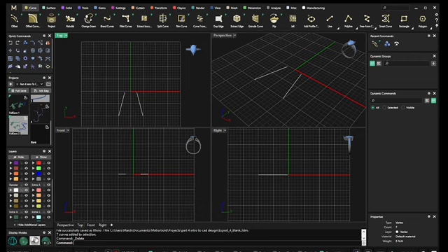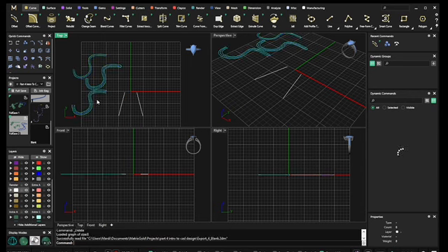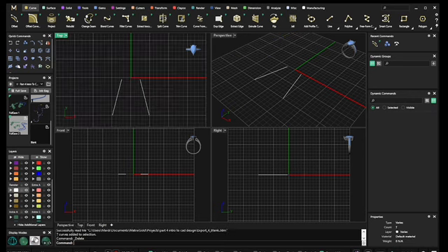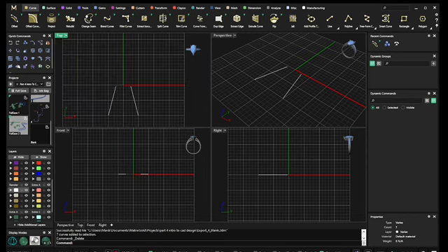So all I did to put it in the job bag as a little reminder was I pressed down on this arrow, and now if I want to bring it back into the viewport, I click in the middle of that job bag and they reappear. So it's a great little holding spot if you don't want your viewport to be cluttered, and you also could put them on a different layer and turn that layer off.